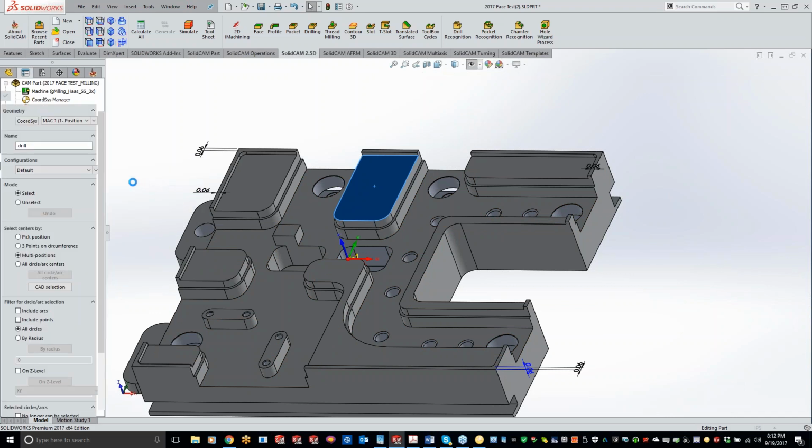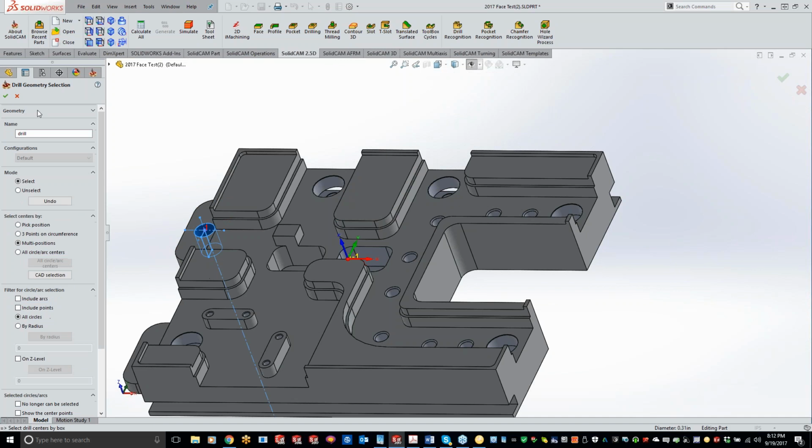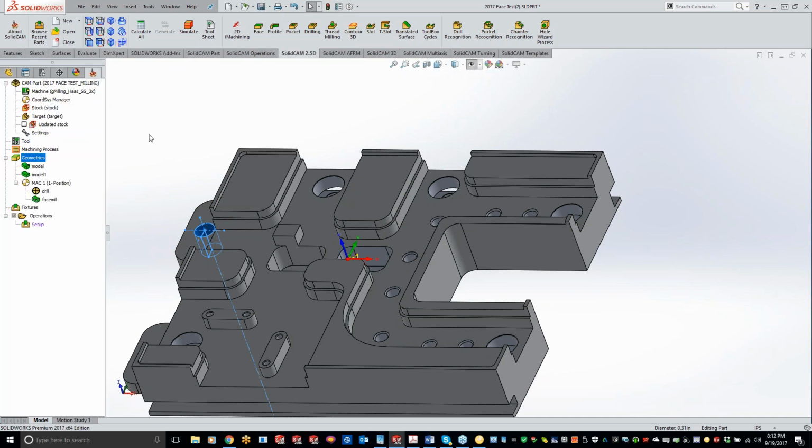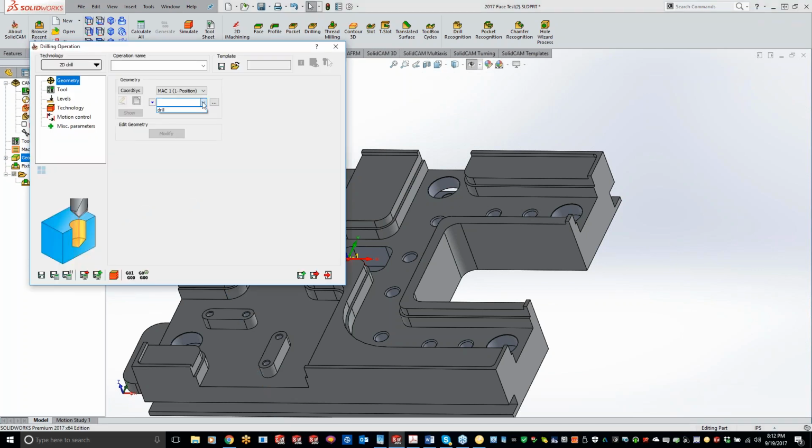If we just did drilling, and let's say we want to do that hole, that geometry is already there for you. So when you come up to do a drilling operation, you can just grab that from the select drop-down menu here. It's kind of nice. I'm not sure 100% why you'd use it, but I'm sure there's a way that I'm not seeing. So that option is there now to add geometry without even adding an operation.